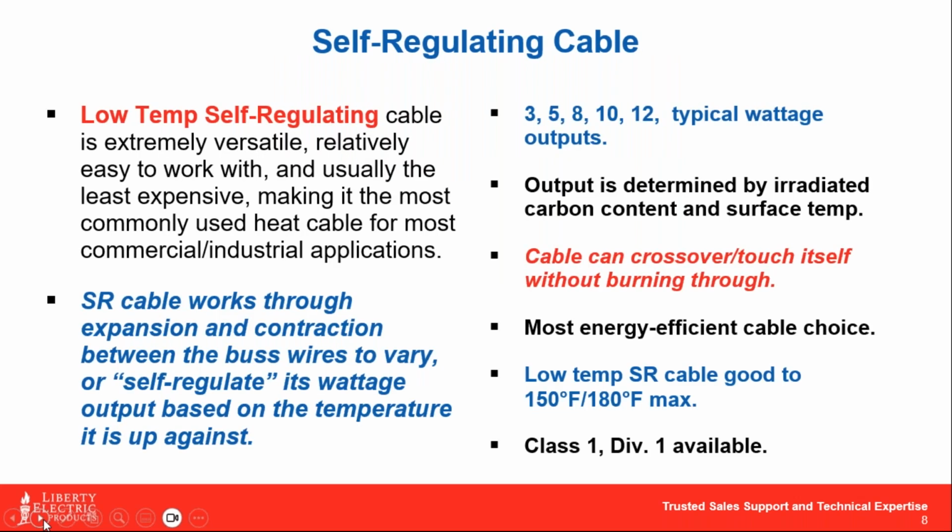All right, so self-regulating cables. Low temp self-reg cable is what you're going to see predominantly in a lot of these scenarios because of the fact it's so versatile. This cable has a great temperature range that it can work within, and basically it's the most energy efficient. There's no question it's the most energy efficient. But because it's the one cable that can actually touch against itself without destroying itself, that alone makes it the most popular cable choice, okay?